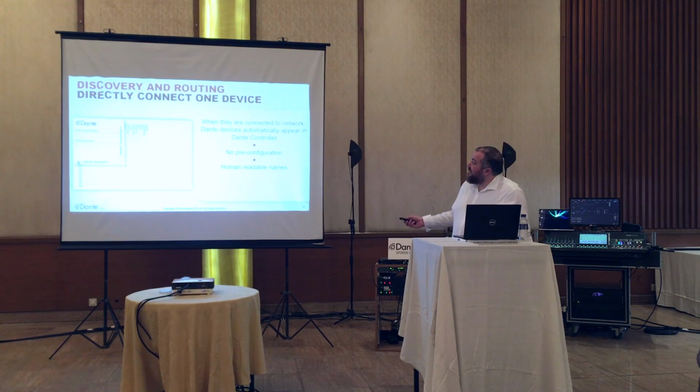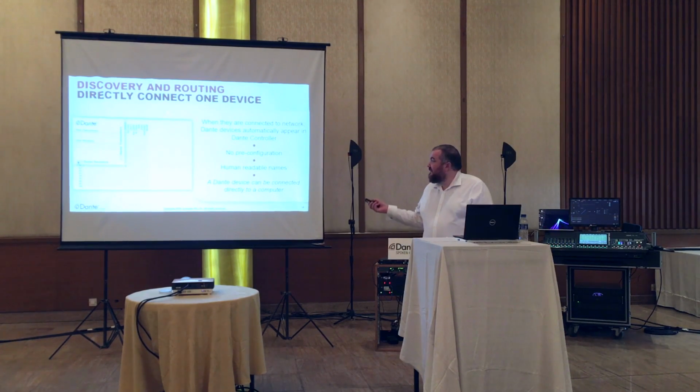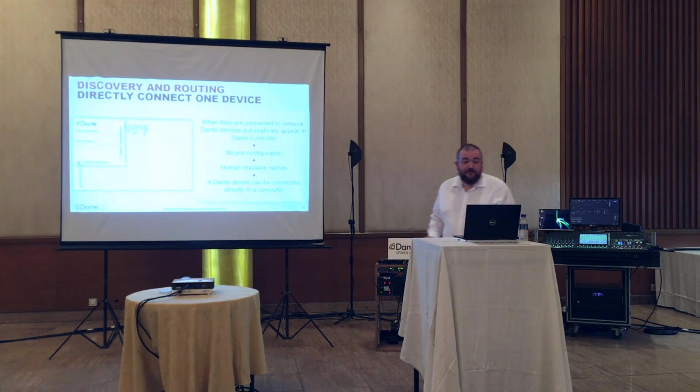We use human readable names, so here we have front of house 1, and for some strange reason someone's using a very unconventional patching technique here, but never mind. But we have the names of the different channels here. A Dante device can be directly connected to a single computer. Indeed, this is how we did this little video. We just took the device, plugged it into the side of the computer, and up everything pops.